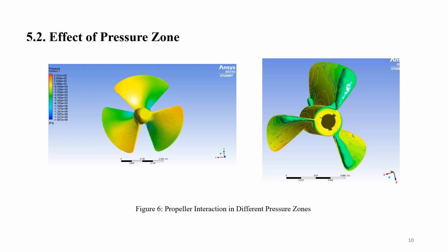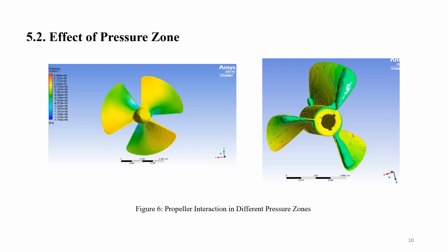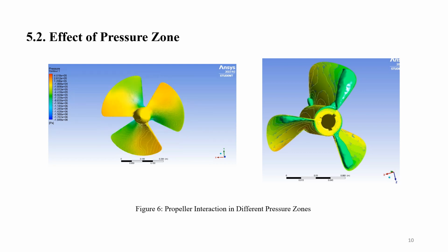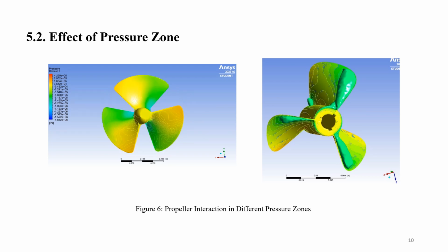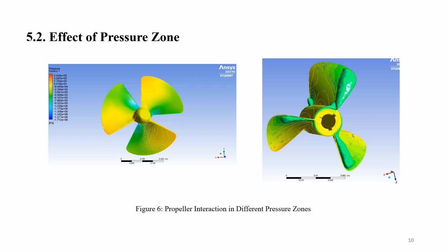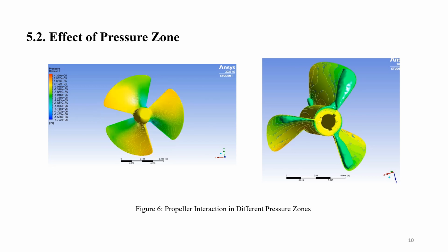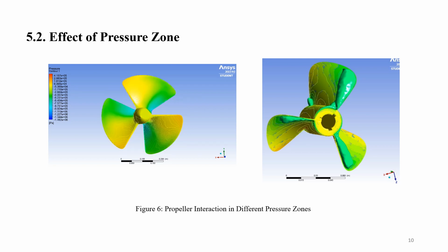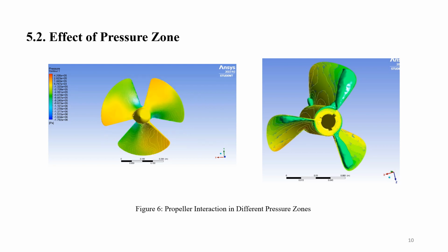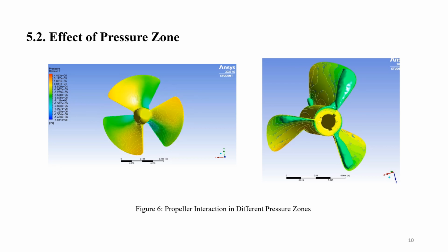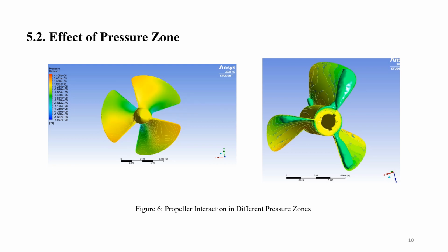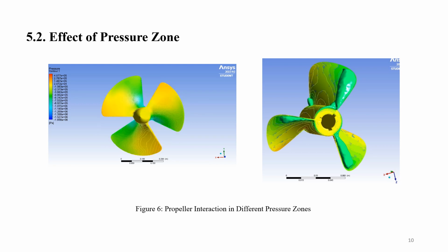The simulation is conducted over a 5-second period, allowing for the observation of the cavitation phenomenon at different time stages. This time-dependent analysis is essential for understanding how cavitation evolves and propagates over time. The vapor volume fraction, a key parameter in cavitation simulations, is visualized using an isosurface. By initiating the vapor volume fraction isosurface, the cavitating zones can be clearly observed and analyzed at different time steps during the 5-second simulation.